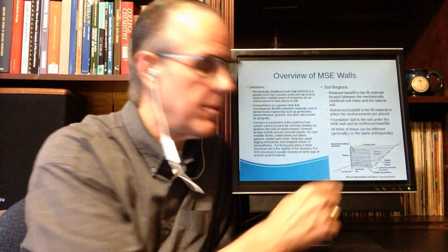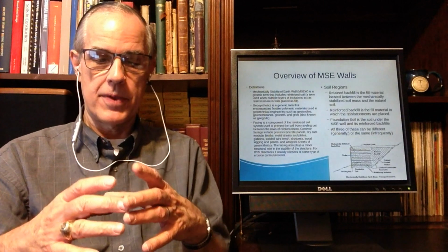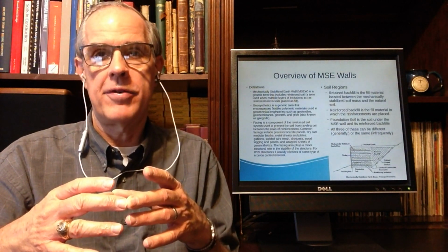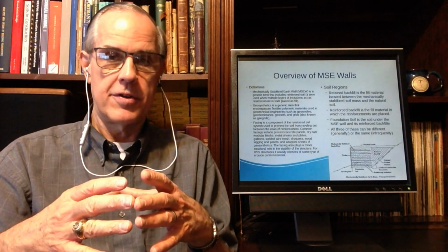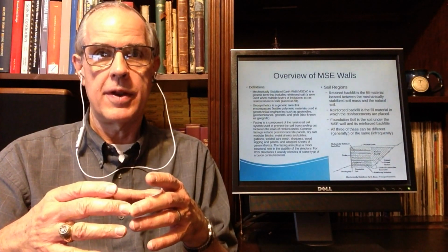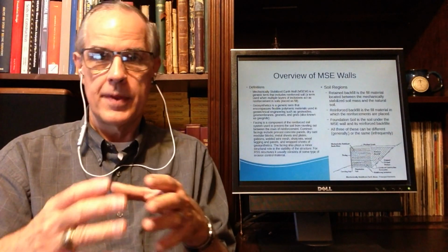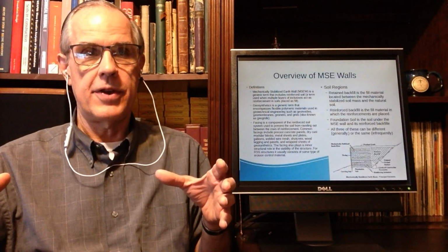To deal with the settlement issue, what they did was they drove a pile that used something very unusual in this geology, which is a pile compacted soil. They actually drove several thousand wood piles into the ground, basically, and we'll talk about cavity expansion when we get to driven piles. As you drive a pile into the ground, it displaces the soil that it's driven into, and that essentially expands.